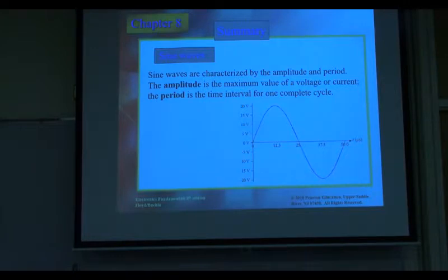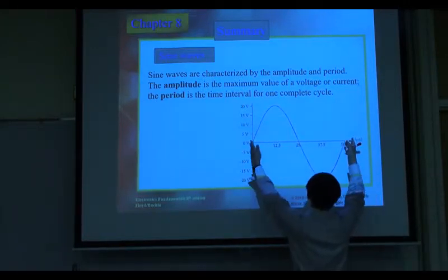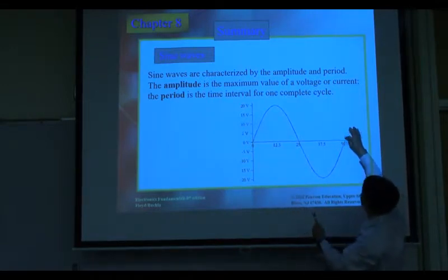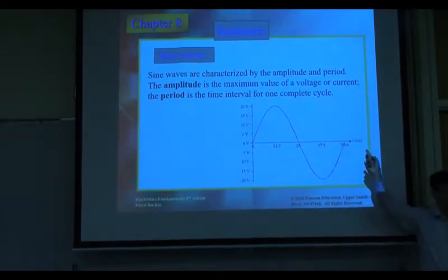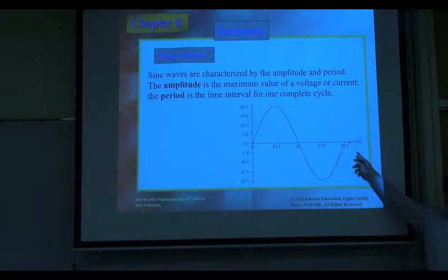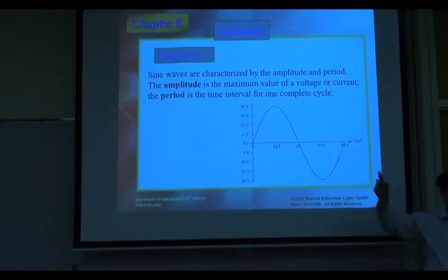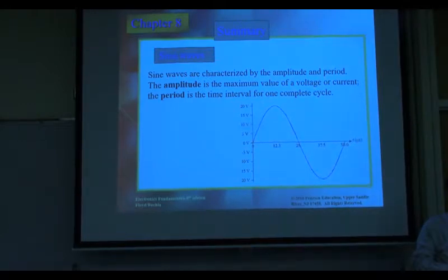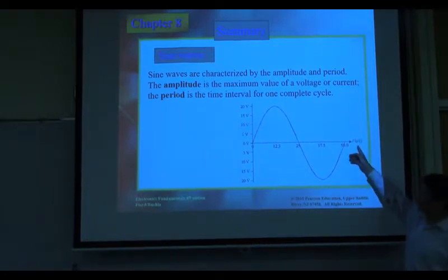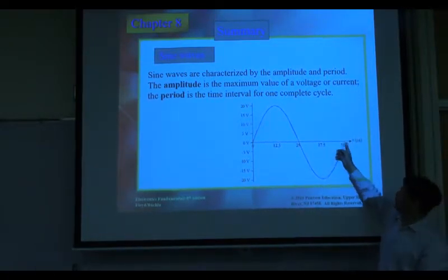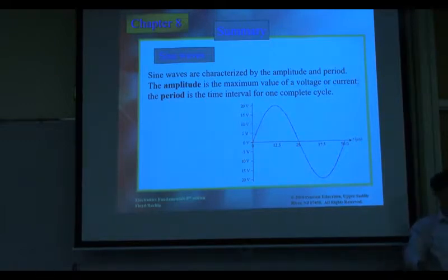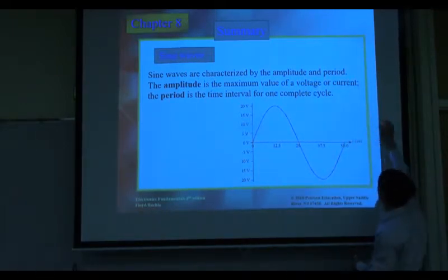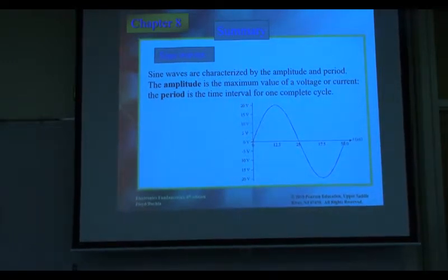And we have one period is from here to here. It's obvious this wave will repeat itself in another cycle, another cycle. So this is called the period. In this example, the x-axis is time. So how large is the period? That means 50 microseconds. So what is the value? 50, right? 50 microseconds means each 50 microseconds, this signal will repeat itself. Up to this point, it will be 100. Then another one is 150.